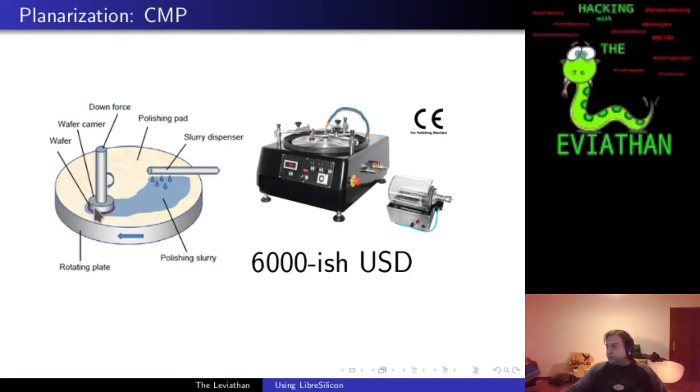So what you have is the wafer carrier holding a wafer towards the surface with some polishing pad. On this polishing pad you dispense a solution in which nanoparticles are dissolved, like for instance ceria, industrial ceramic. Then you apply a well-defined pressure, which you set in the control panel of the CMP machine.